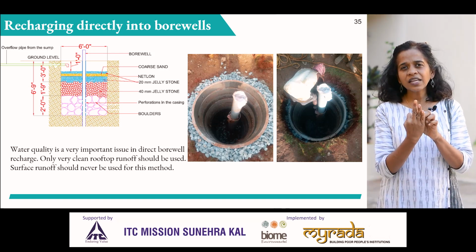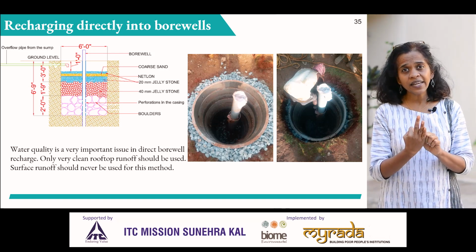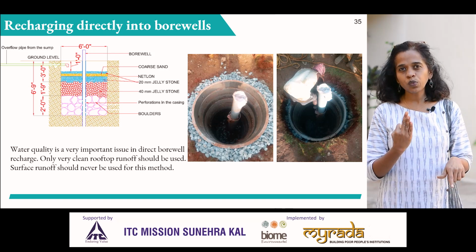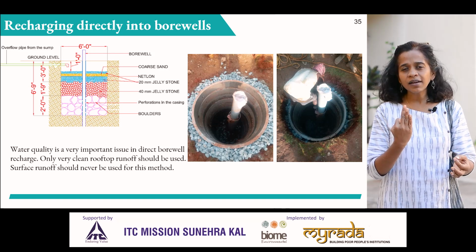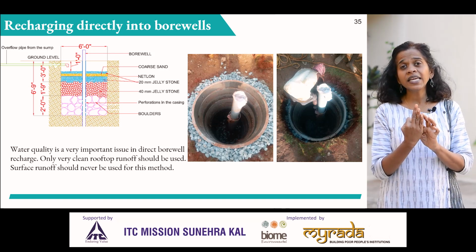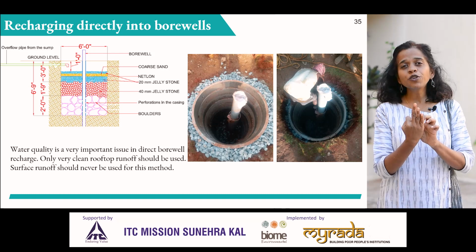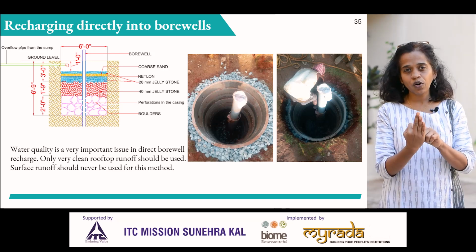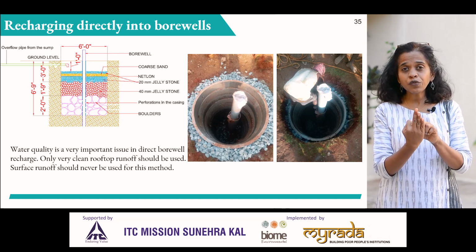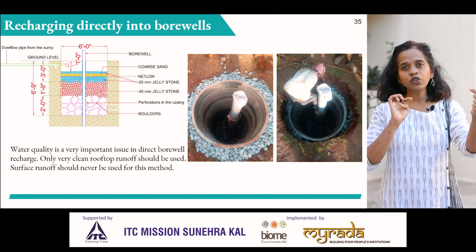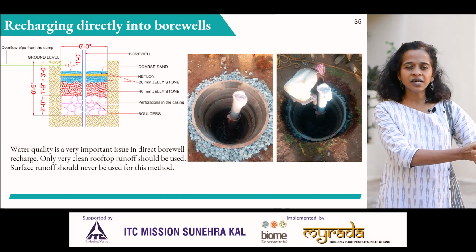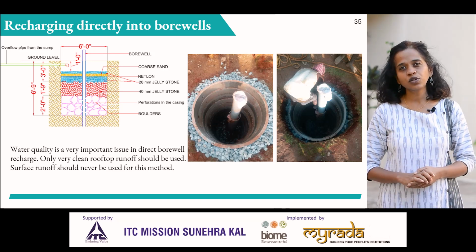We advise that if a borewell is currently yielding, don't try to recharge a borewell, because sometimes it may result in the motor getting some movements, because of which, in case the water source stops, you may blame your rainwater harvesting for it. So it's advisable, if you're doing recharge for a borewell that is currently yielding, don't make perforations in the casing, but just dig a recharge well adjacent to the borewell.